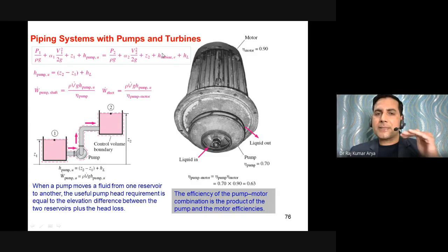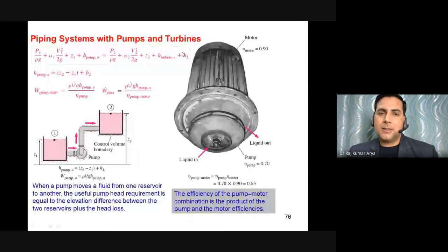The turbine always extracts the energy, the pump always imparts the energy, and whatever losses there are, all the losses have to be added to the exit end, or point 2. This is how you have to use the energy balance. This is the common equation; you must always know it. There is nothing great here. This is nothing but your Bernoulli equation, but you are adding it for the non-ideal case. So you add a kinetic energy correction factor, pumps and everything.